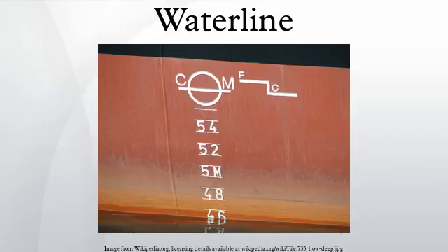The winter North Atlantic load line is used by vessels not exceeding 100 meters in length when in certain areas of the North Atlantic Ocean during the winter period. When assigned, it is 50 millimeters below the winter mark.